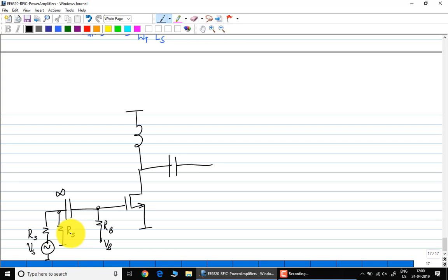So in other words, what you're talking about is exactly equivalent to putting a transformer at the input. By the way, a matching network is almost the same as a transformer. So all you're saying is get some passive gain. Of course, that is definitely possible. I could even put a transformer here, before this, right? Instead of putting it to the left side, I could always do that. Getting passive gain is not a problem. Getting power gain is a problem. Getting active gain is not a problem at all. I mean, getting passive gain is not a problem at all.